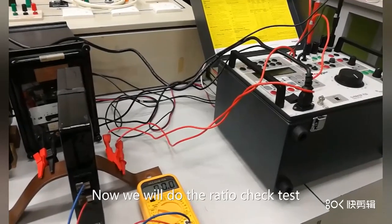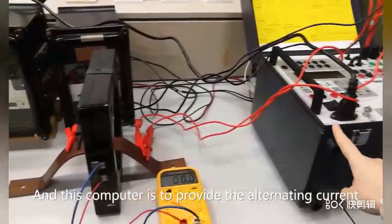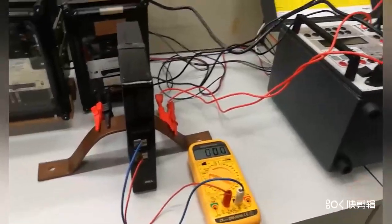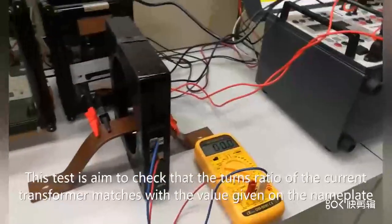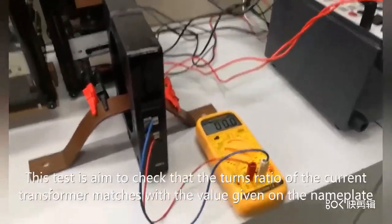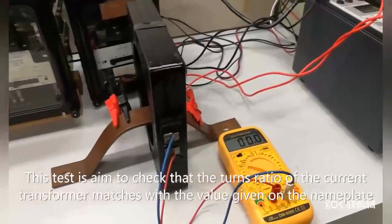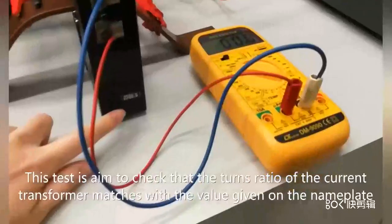Now we'll do the ratio check test. This computer provides the alternating current, namely the AC, and here are the multimeter, the current transformer, and the bus bar. This test is aimed to check that the turns ratio of the current transformer matches the ratio given on the nameplate.